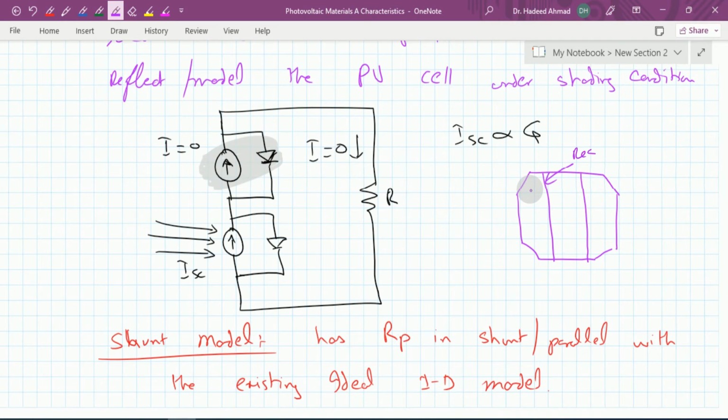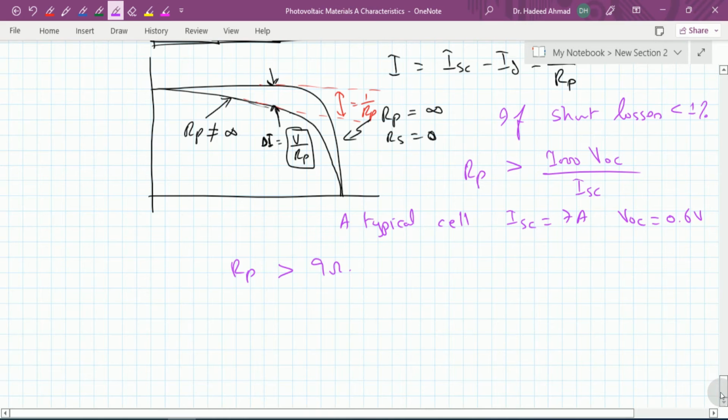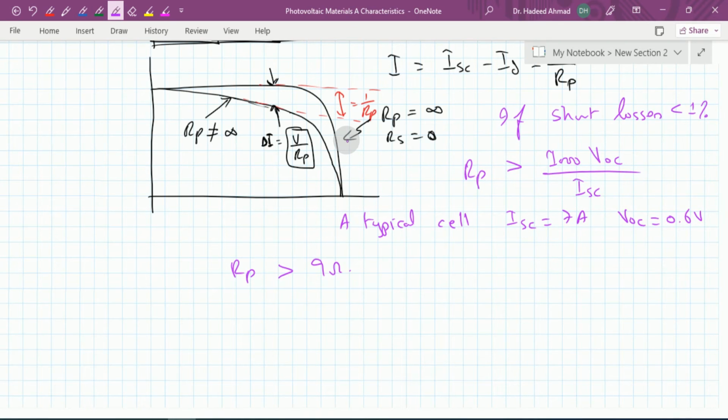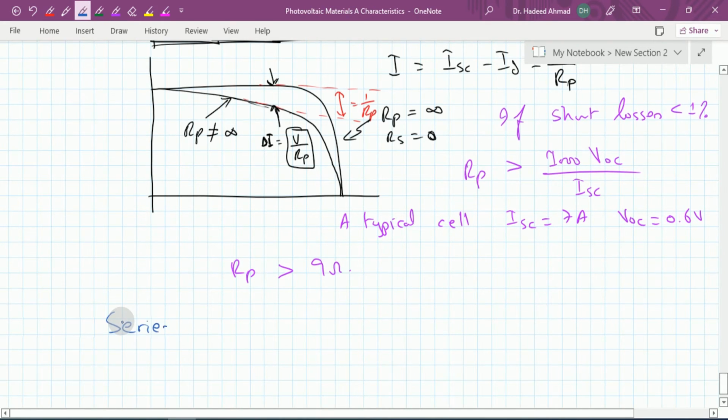Their resistance also accounts for a loss in the system. So let us first model this particular loss before we create a comprehensive single diode model including the impact of this parallel resistance and the series resistance. This particular model is known in the literature as a series PV model.